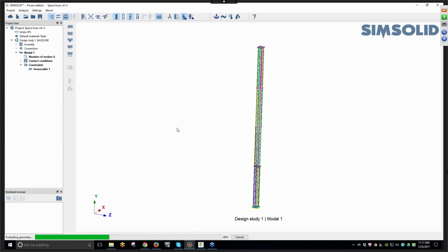So now what happens is it creates, as I said, this initial equation set. It solves it multiple times. The default solution setting for SimSolid is 3 passes. And each pass, it evaluates the errors and then enriches the solution locally and repeats. So that's pass 1, that's pass 2.